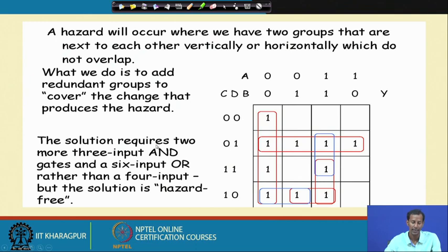The meaning of that is, this kind of thing may happen unintentionally in your circuit, and it will be observed whenever you do timing simulation. For the functional simulation, this kind of thing will not be recognized or noticed. Only when you are doing timing simulation will these hazards be noticeable.